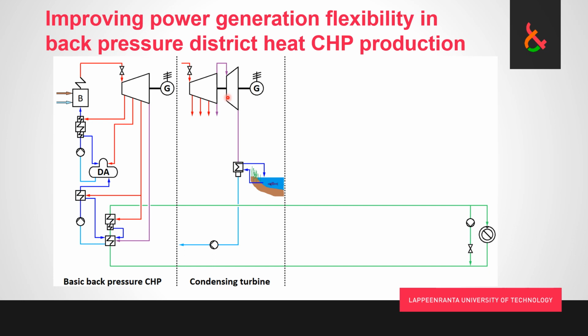Now, the drawback of this situation is that this is fairly expensive. So we have the very large turbine back end. We remember large volumetric flow rate means huge turbine, long blades, large casing. Then we have a very large condenser. We have seen those pictures in lecture number 3. So we need to give a lot of space for the steam to be able to flow into the tube bundle. And then of course we have to build the cooling water supply, and all that is going to cost a lot of money.